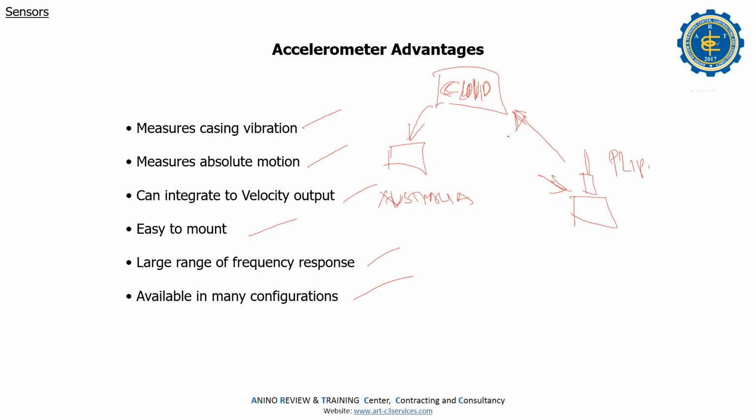Is it good or bad, on your side? We are condition monitoring engineers, so I think it is bad, because you can't feel the equipment. You don't know how the equipment looks. You can't tell the structure, and you can't see the cement grout. Sometimes you get the vibration from the cement grout also.